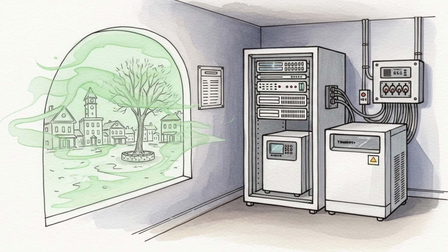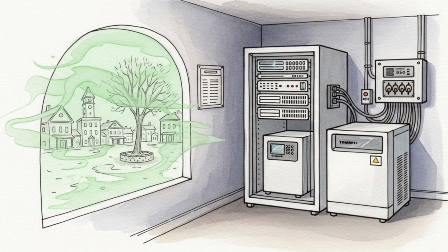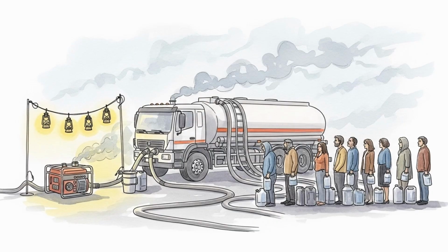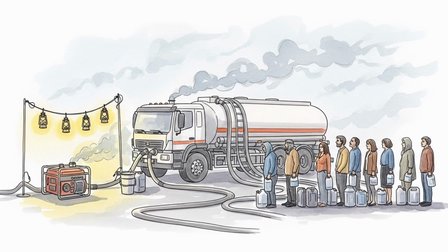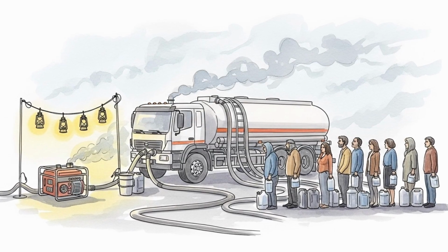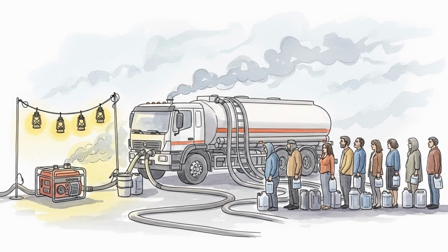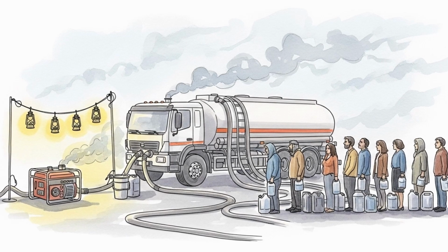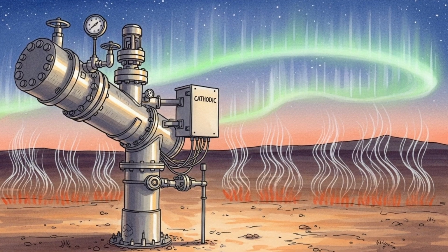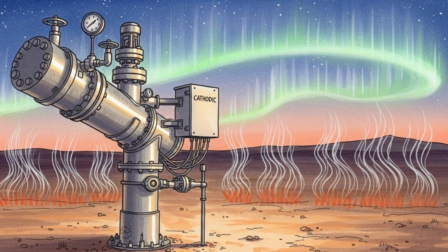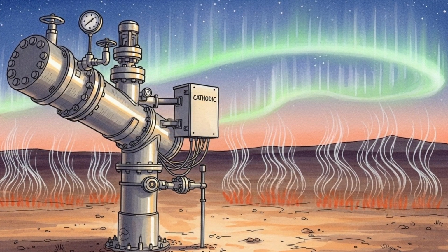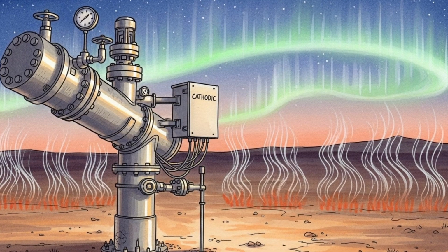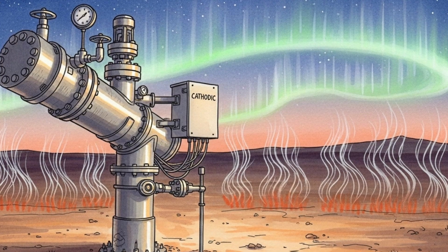Temporary workarounds: mobile generators and mobile reactive devices support substations and data centers. Portable high-stability clocks maintain local time where satellite timing is degraded. Terrestrial precision time protocols and synchronous Ethernet distribute time when satellite signals are unreliable. Satellite phones and line-of-sight radio provide voice fallback where high-frequency paths are blacked out. Store and forward and local caching reduce sensitivity to intermittent links. Public status pages and broadcast messages are mirrored across multiple platforms.